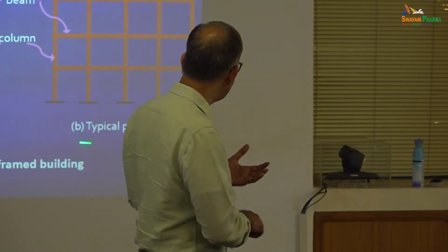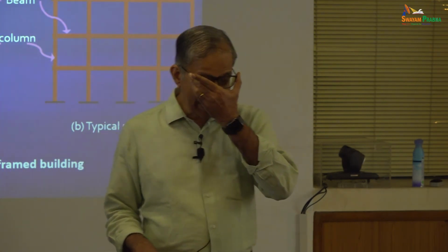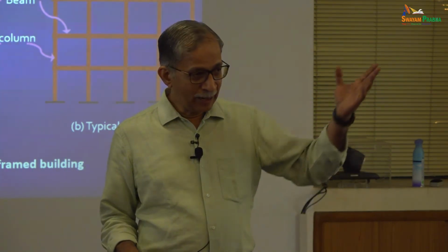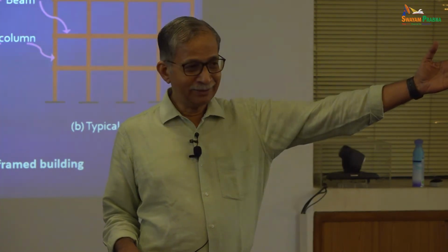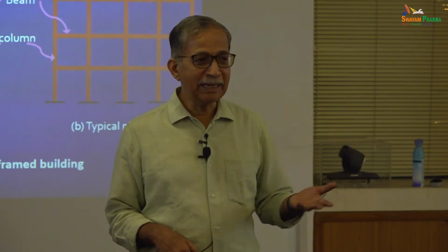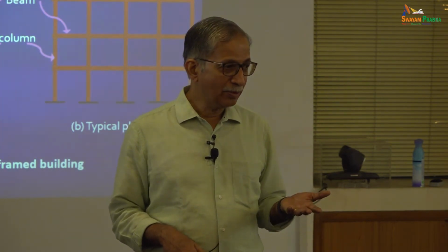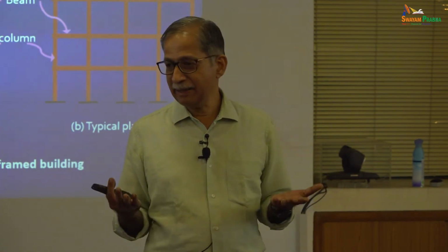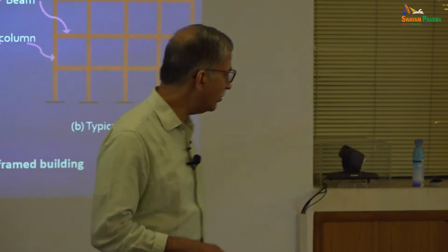The shear force, that's why we talk of base shear, and you'll find this is one error many engineers make. They think column has to take mostly vertical loads. So you have very small sizes given to columns in flats. You can see here 230 mm by 230 mm. There's no way it can take the shear caused by earthquake loading. So you have to be sensitive to the fact that you need a certain plan area, cross-sectional area, which should be adequate to take the base shear and the bending moments.